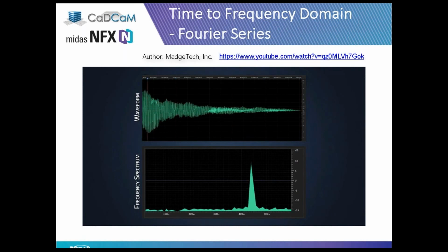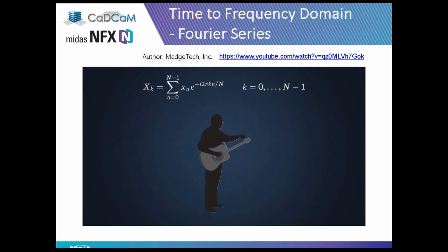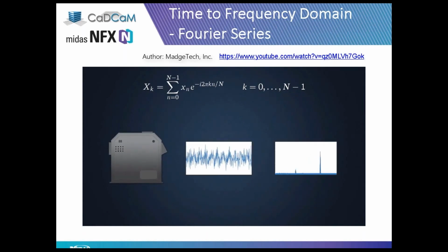The frequency spectrum measures amplitude over a spectrum of frequencies rather than time. We can see that this frequency is holding at about 440 Hz, which, if we're still talking about music, is an A note. If this A note showed up oscillating at a frequency of 400 Hz instead of 440 Hz, we would know that the musical instrument is out of tune and needs to be fixed. Now, you wouldn't use the fast Fourier transform to tune an instrument, but this example is similar to the method used when monitoring machinery vibration. By dissecting signals into their individual frequencies, we can determine if any parts of the machine are malfunctioning.